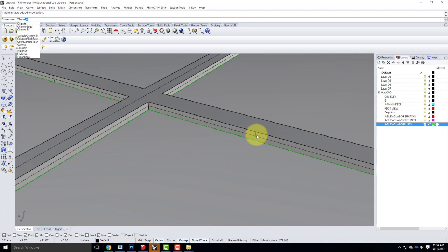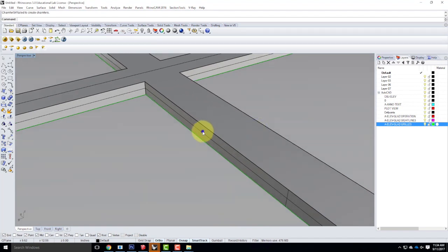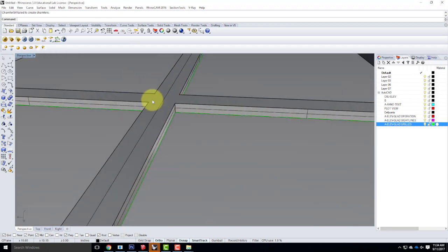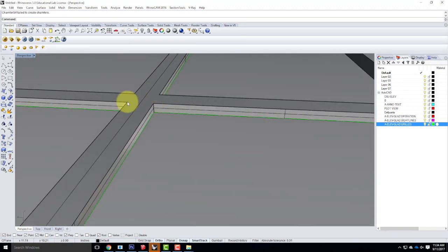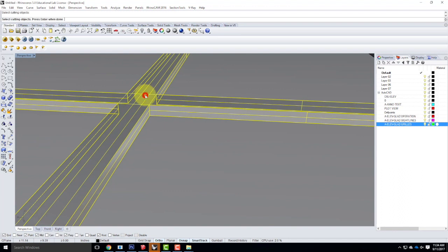So we're going to add a little bit more detail. I'm going to do a chamfer surface. My distance is here. Let's do 1/8 of an inch. So 1/8 inches. There we go. And let's go ahead and chamfer this one to that one. Oh, how nice. It failed to create it, right? Thanks so much. All right, in that case, I might have to split this back. Did all that work to not do this, but split with this.